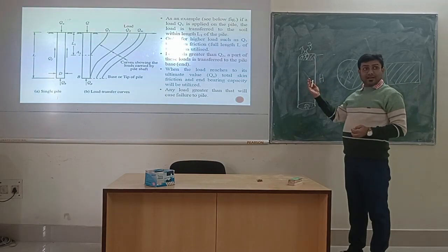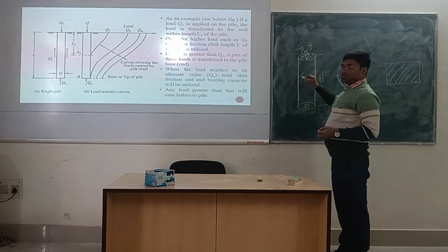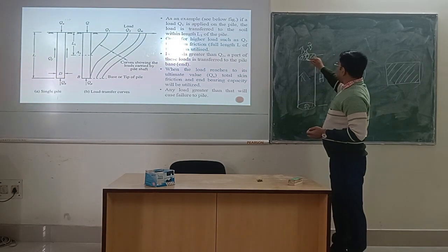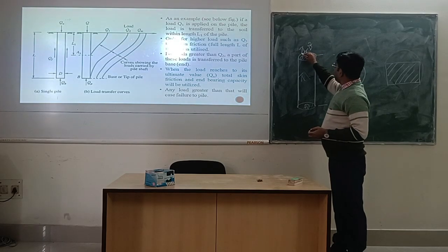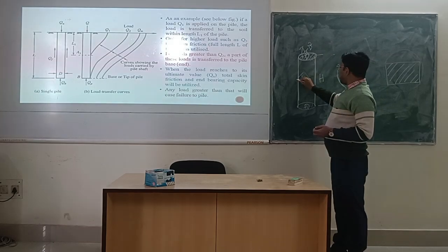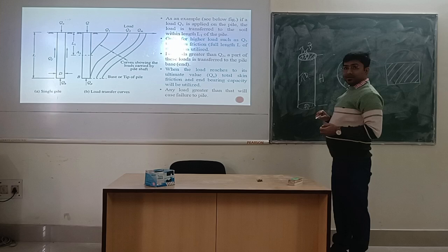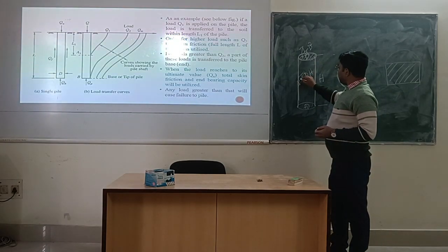Okay, and you have already told me what the surface area, the pile surface area, the shaft area is. Pi d square? What? Only pi d square? No, not pi d square h. This perimeter, what is this perimeter? 2 pi r, that means pi d, and h. This is the shaft area.